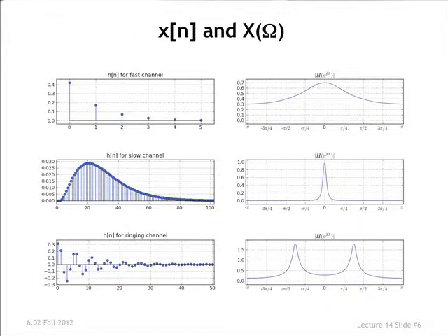If you look at the top plot in this set, the top plot is exactly a signal of that type, except I've chosen a different number. Instead of 0.5 to the n times u of n, it's something else. But here's a discrete time exponential or a geometric series. Now I've just plotted the DTFT from minus pi to pi to show you what the spectral content of the signal is.